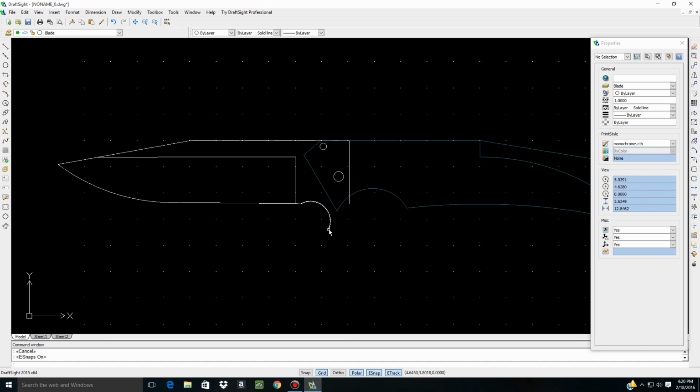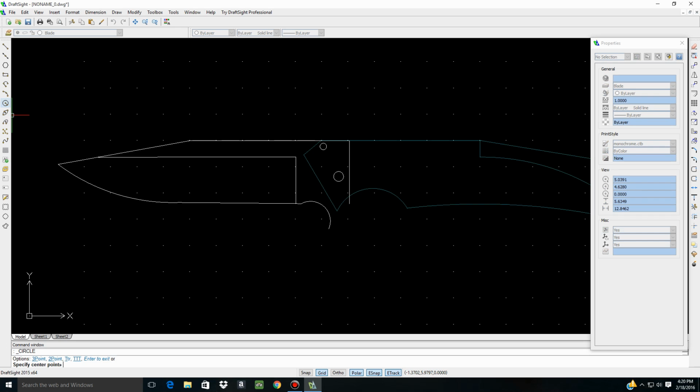Now we want to radius the end of this. Right? So now we know our 3/4 inch wheel will easily make this radius here. So now we need to make the back side of the flipper. Now, if you want to get fancy, you can match it up to the curve of the handle. That's completely up to you. Some guys don't bother. Some guys come straight down. They want to do something like this. That's fine too. So we could do another 3/4 inch circle, let's say.